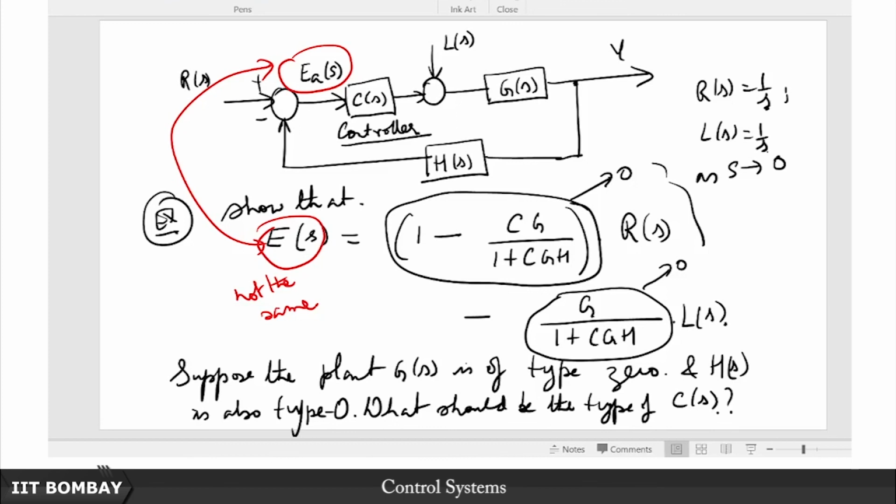It tells us exactly the distribution of the roots. So how many are on the left half plane, how many are on the right half plane, how many are on the imaginary axis. We can actually get a complete picture of this, okay. And the good thing about it is something you can do using hand computation. You will not need even a calculator in most cases.